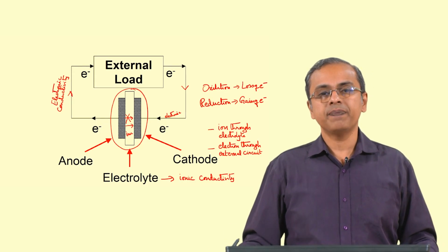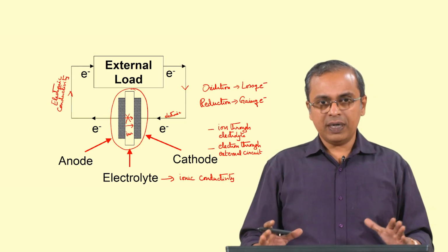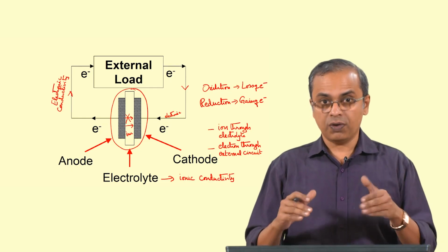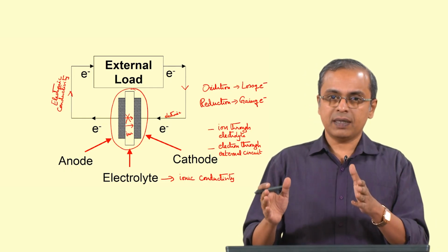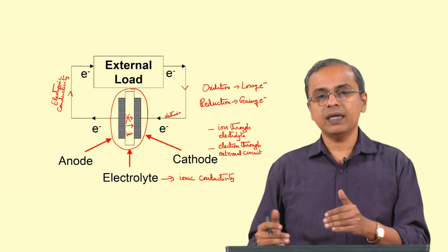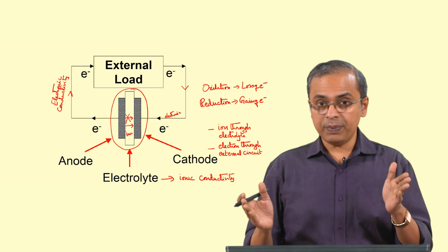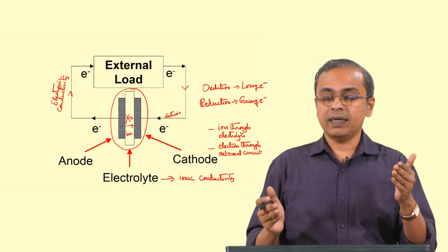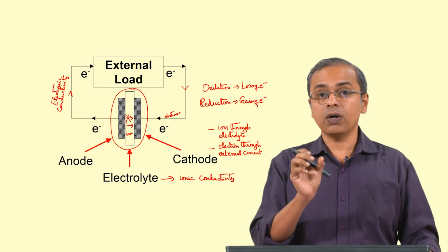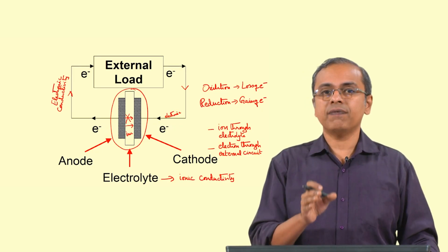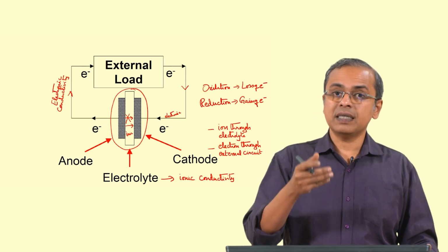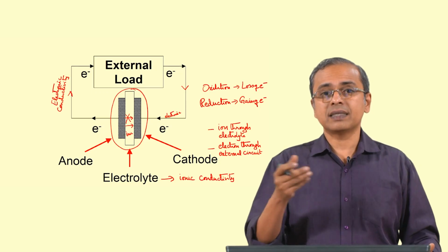Okay. So the summary of what I am trying to describe here is that in a typical circuit that involves a power source of this nature, there are parts of the circuit that have to have electronic conductivity and other parts that are supposed to have ionic conductivity, and you have to be careful to ensure that a component such as the electrolyte must not have electronic conductivity. Sometimes as the material deteriorates for various reasons, it may develop electronic conductivity, and that is considered bad.